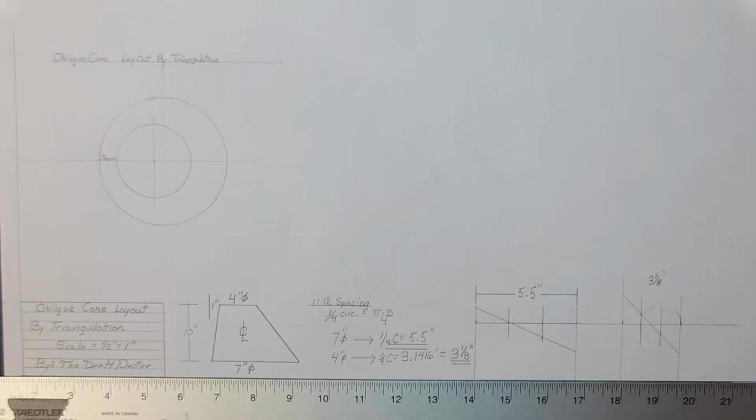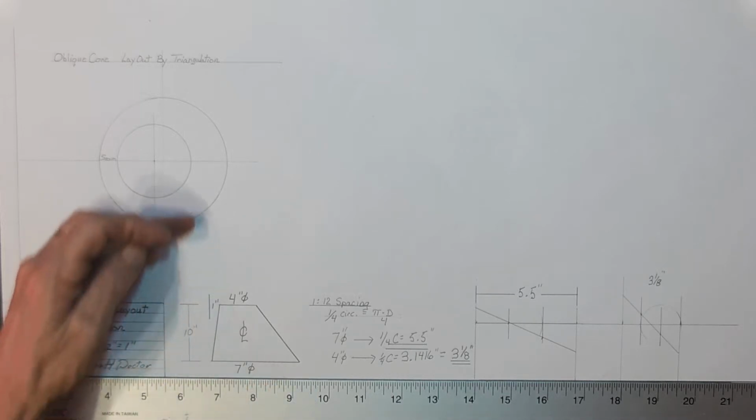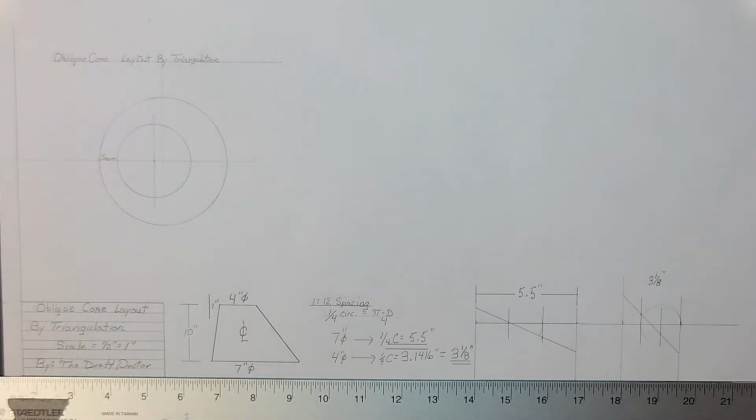However, in order for me to use radial lines, the apex has to be within a working distance. When the apex of this cone is off the page or somewhere on the next block, I cannot lay it out with radial lines. Therefore, I must triangulate. Triangulation is the go-to for most difficult layout, and it is quite simple. The method of triangulation is defined as finding 2 points from a known point.